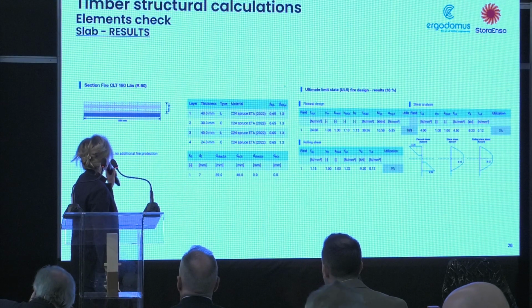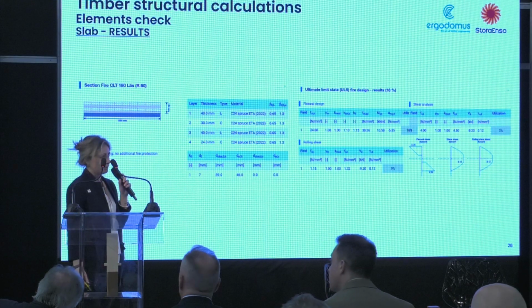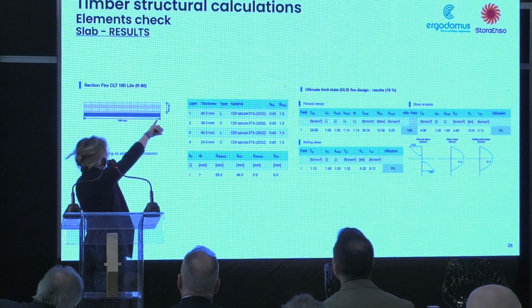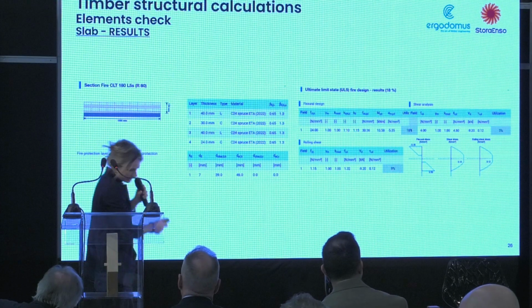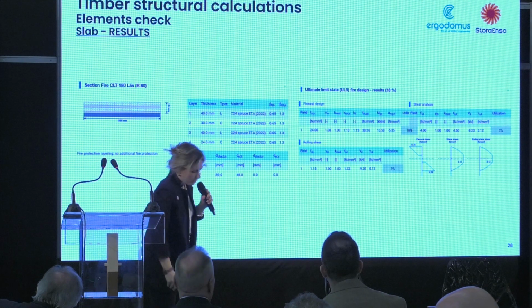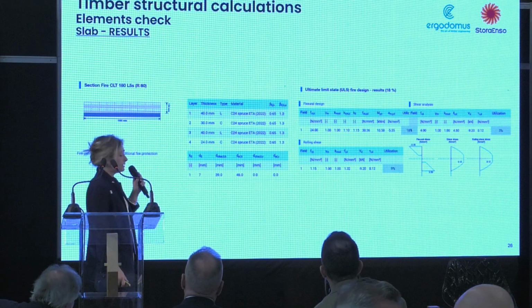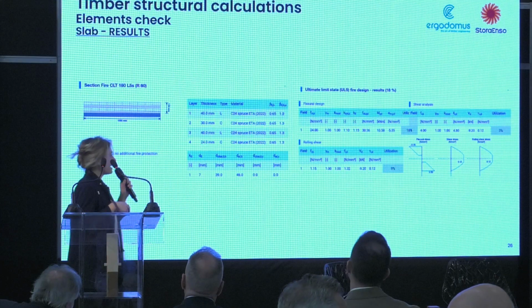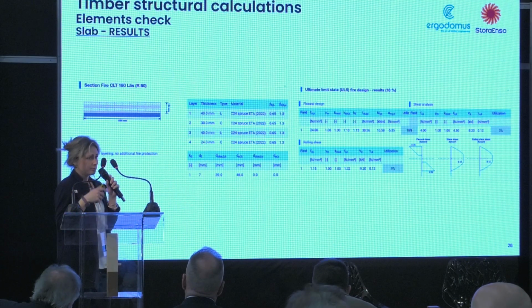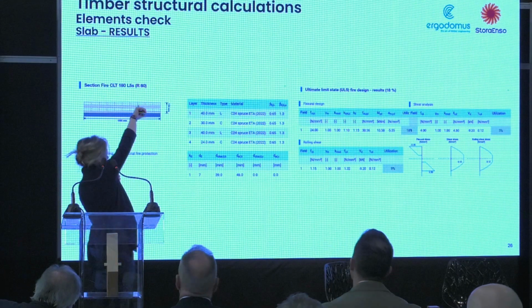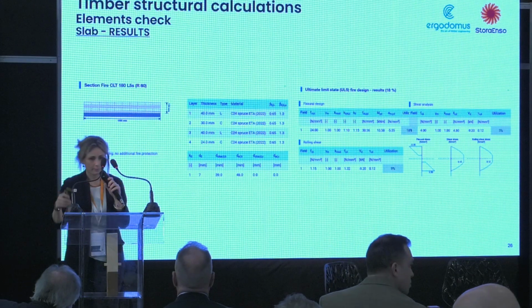You can also have the final section in case of fire. In this case, we have an estimate of, I can't read, an estimate of 134 millimeters after fire, and we have considered here R60. So it means that after 60 minutes, you still have all this material as load-bearing material.